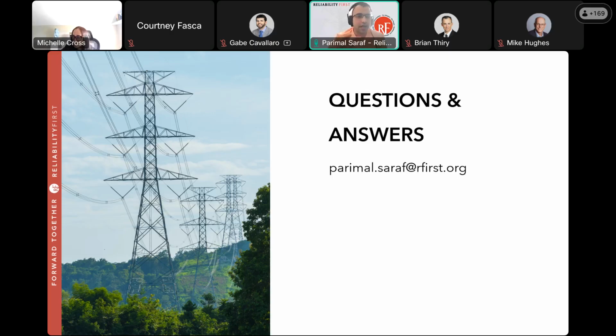So it doesn't allow the frequency to change that much because of its physical form. That's the main inertial response that we get from a synchronous machine or a conventional machine. Now, IBRs don't have that physical device, but they can replicate that behavior by injecting active power extremely fast, right?